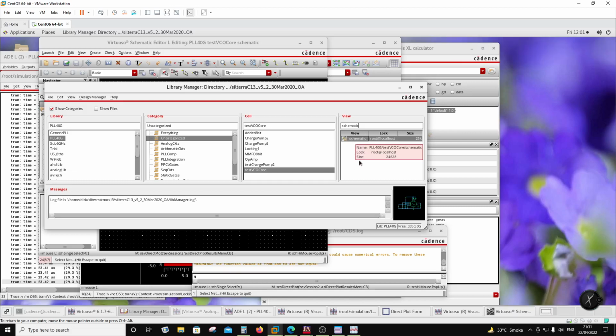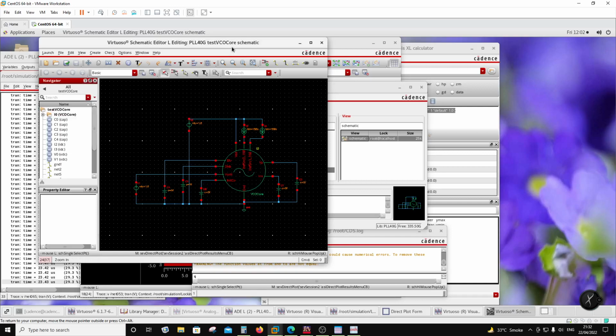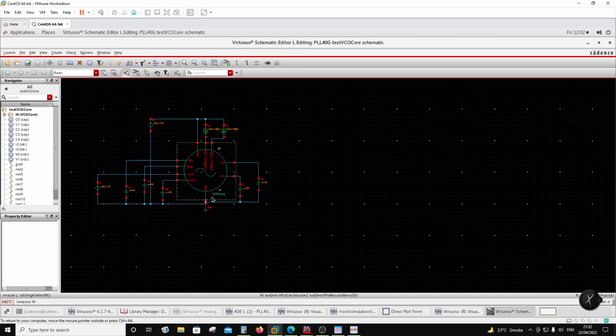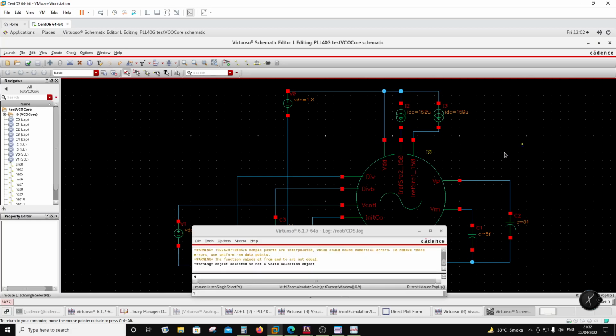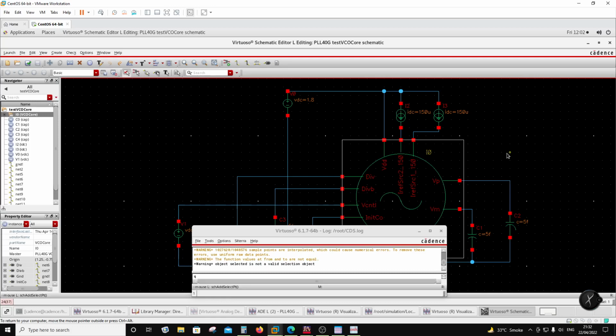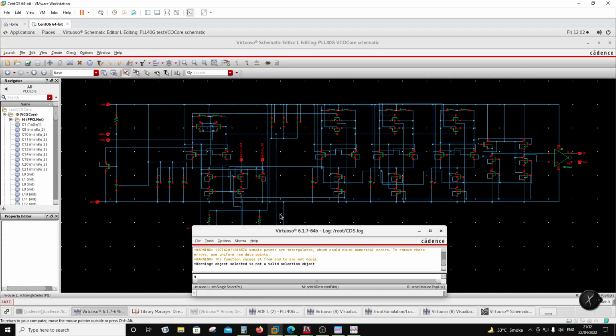Okay, I'm going to show you whether the injection locks are working and whether the locking is correct, right? So that's your VCO, right? And this is my control voltage here, right? It's driven from 1.8 volts. These are the bias currents, and inside this is your VCO. Of course, there's no information yet on this simulation. Okay, so that's the VCO which we talked about.